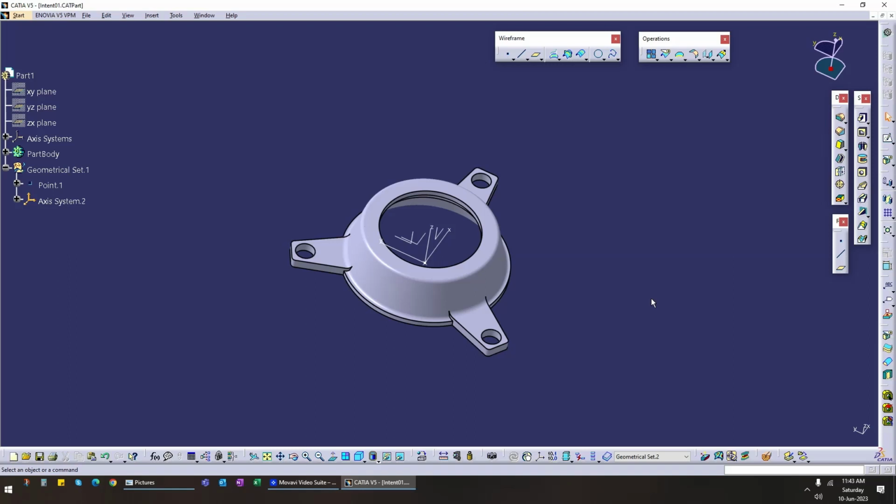The 3D model that we create must be easy to edit and easy to customize. And in the end, we should avoid using negative operations. Instead, we should use Boolean operations because it will make our specification tree more simple.